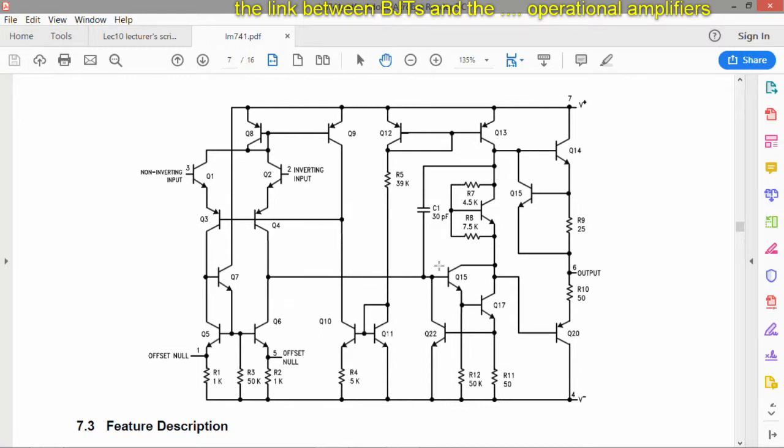You can see that in this kind of applications, people don't want to use capacitors in cascading things, because, as I said, this will have bad effects on the overall bandwidth of the circuit. Actually, the operational amplifier amplifies also in DC. And this is the reason why people don't want to put capacitors in. That's why this is all DC coupled.